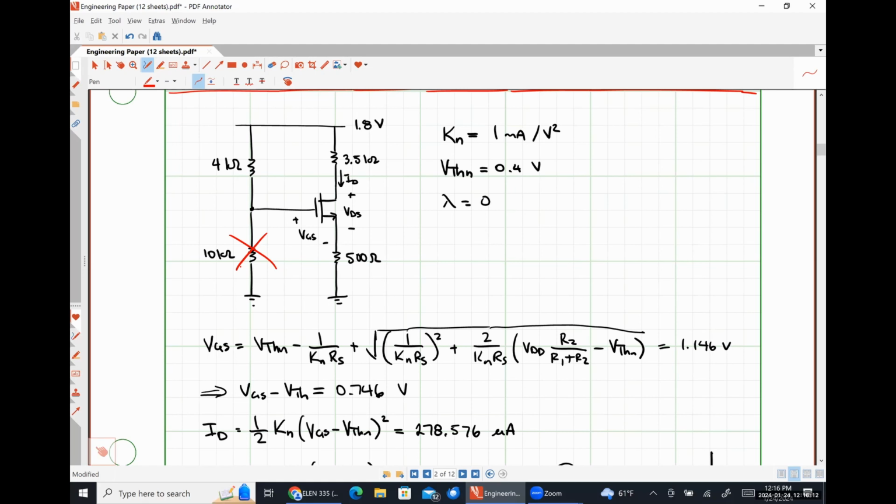So we should see that the gain on this is positive, and it's usually very, very close to 1, usually somewhere in the ballpark of 0.9 to 0.95, depending on what the parameters are and all that kind of good stuff. But I've never seen a source follower where you did not have a source resistance right here, because the degeneration provided by the source resistance gives us the nice stable operating point and all that kind of good stuff.